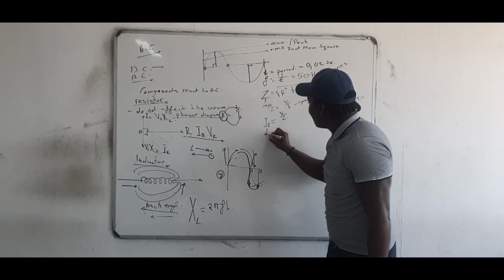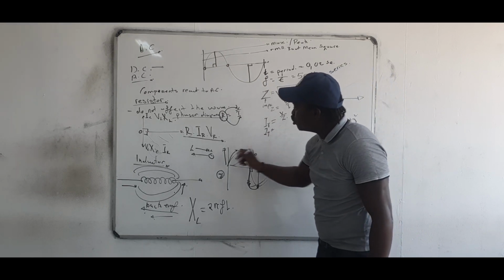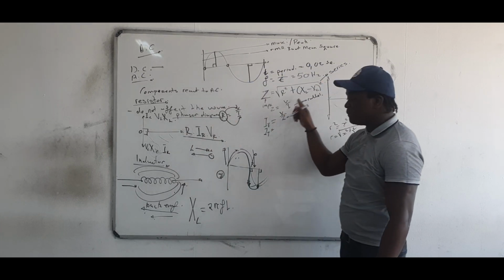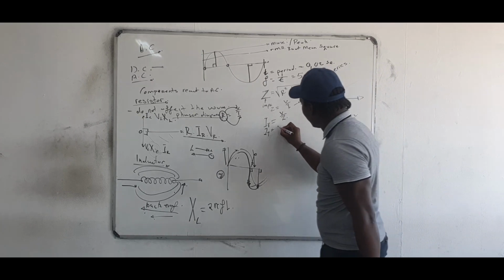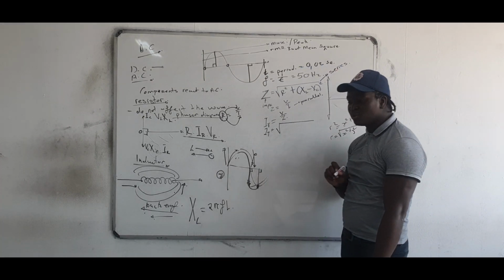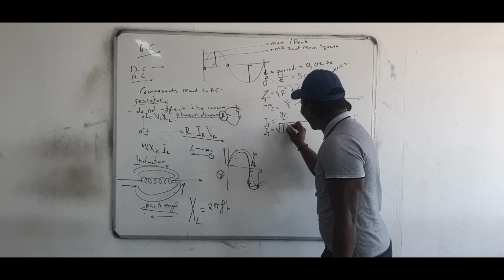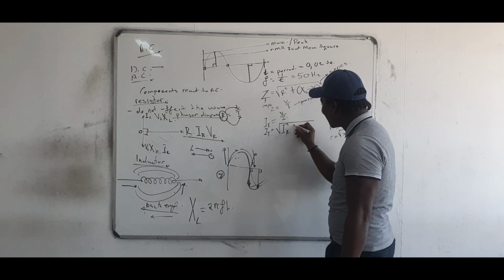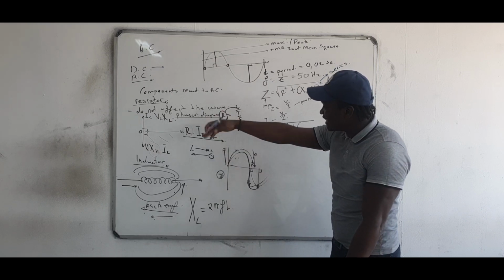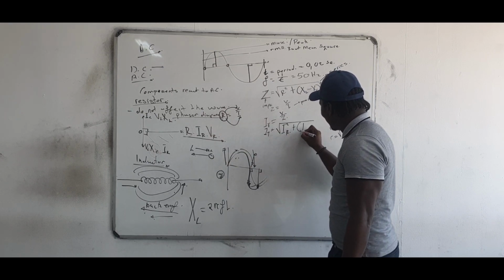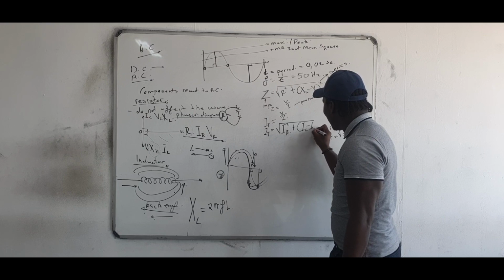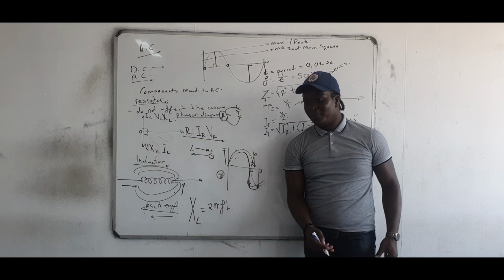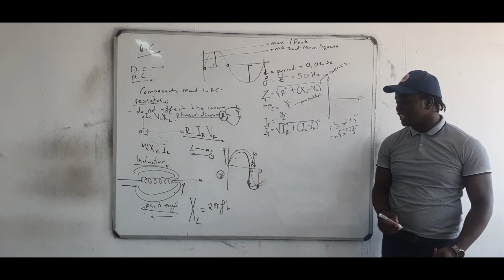Also, if it is now a parallel circuit, how do you add three currents that are going in different ways? We do the same thing. Are we together? Pythagoras theorem. So here we're going to have our IR squared. Are we together, right? Because we are adding, but we're adding things that are going in different directions. And then it's going to be (IC minus IL) squared. I always want us to start with the one on top. I just want us to have it in our heads that you always start with the one on top.